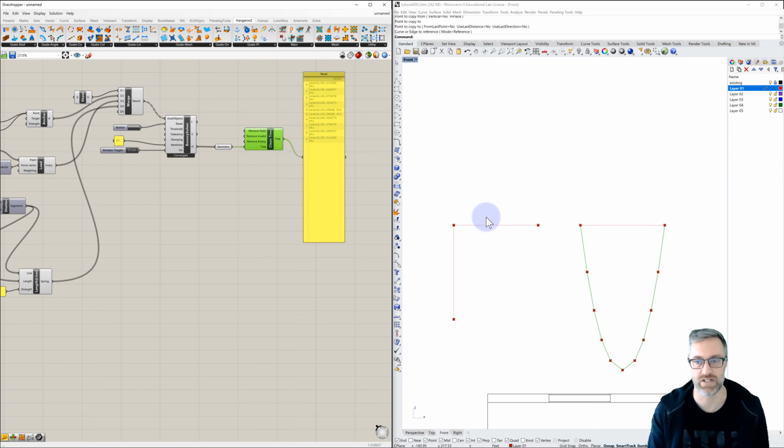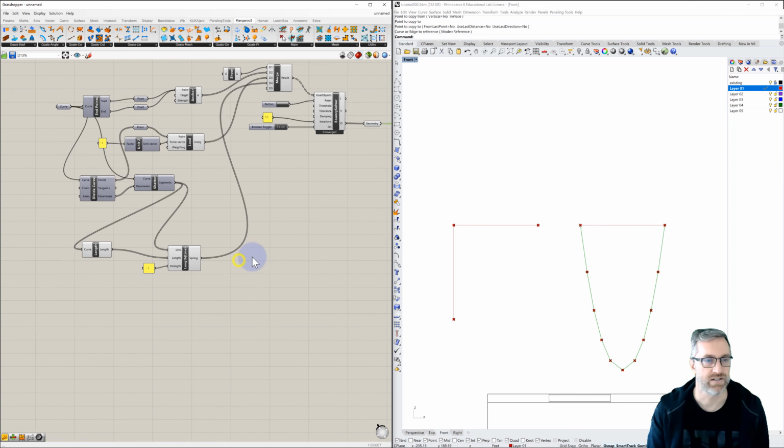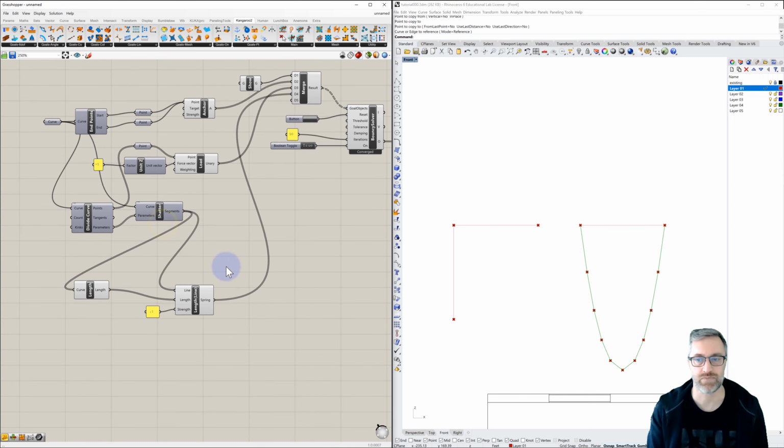We don't need to compare them because we can see visually what's happening. But let's look at the way that that changes. And this is a really nice demonstration of what I would kind of call tributary area or tributary loading, because each one of these points has a load applied to it. So this means, and what we see happening successively is that this cable, this element, is stretching more because it has the load of 1, 2, 3, 4, 5 loads pulling down on it.